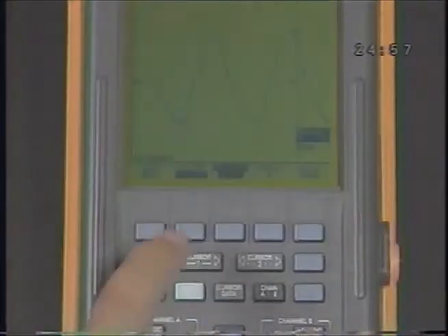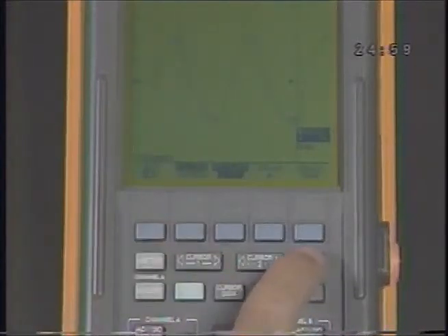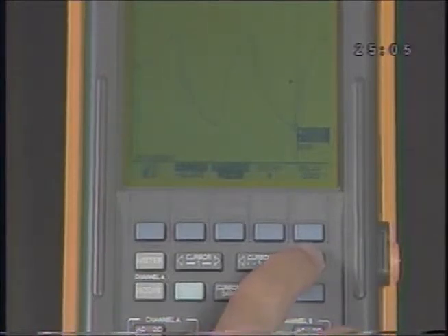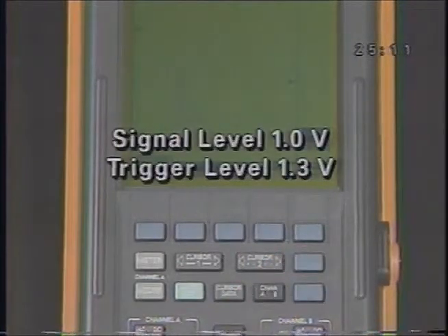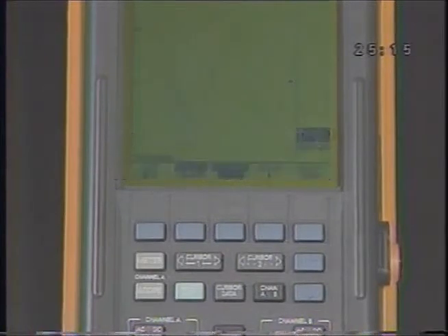Switch back to positive slope and try to increase the trigger level. The signal isn't really moving. Scopemeter's just starting to trace the waveform at a higher voltage. If you keep increasing the trigger level, you'll soon exceed the voltage signal being generated. What happened? Earlier we said the Scopemeter wouldn't display a waveform if the signal didn't cross the trigger. How come you still have a waveform?